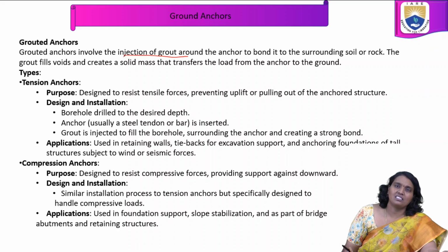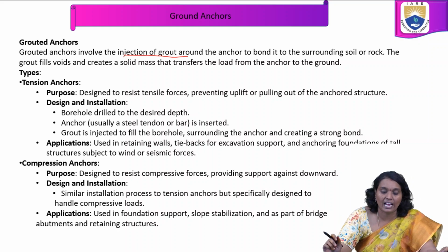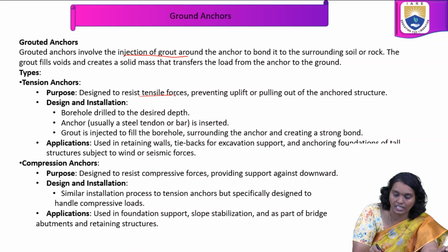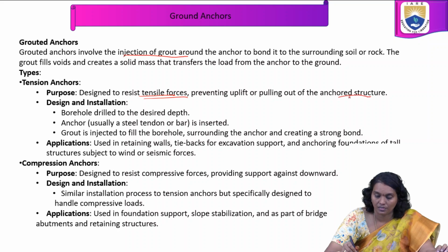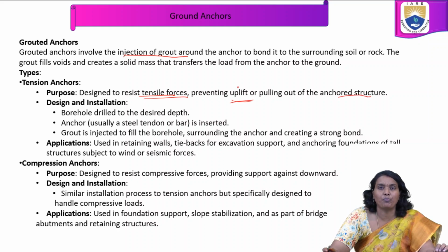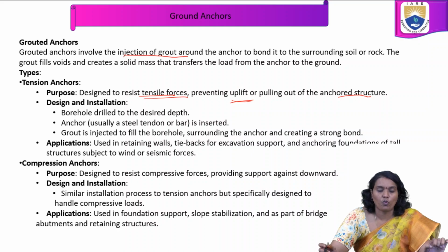Tension anchors are designed to resist tensile forces, preventing the uplift or pulling of the anchored structures. For design and installation, a borehole is drilled to the desired depth. The anchor, usually a steel tendon or bar, is inserted.